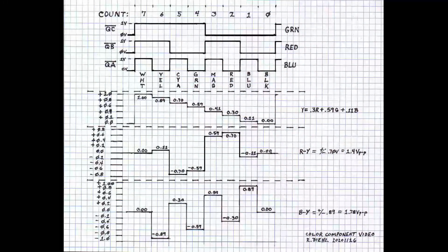Color programming was rare. So RCA and a think tank called the Hazeltine Group did the preliminary theoretical work to create this signal system that allowed black and white televisions to show a color program in black and white, and a color television to show a black and white program in black and white, and of course a color TV to show a color picture in color. So the first thing that they did was derive Y, the signal called Y. This is an arbitrary symbol assigned to the black and white component of the signal. It represents the brightness information.